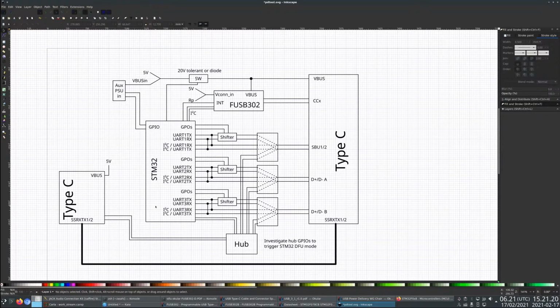Yeah, about breaking out the boot pins to jumpers, don't worry about that. It's implied in all of this because I hate how all the other breakout boards don't do this. Any pin that has a useful function that is not being used is going to be broken out to some kind of jumper. If I can get away with it, every single unused STM32 pin will go to at least a test point that you can solder to, unless I really run into space constraints. And definitely the boot stuff will be on jumpers, so don't worry about that.